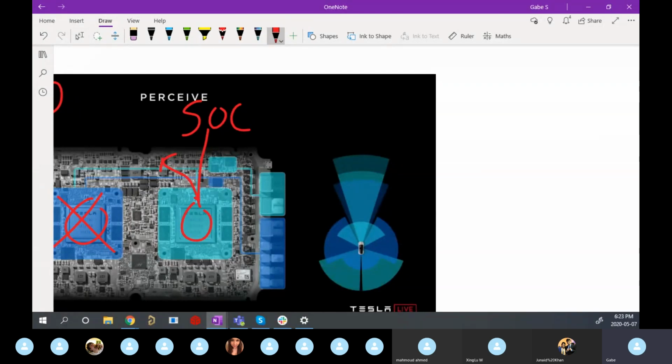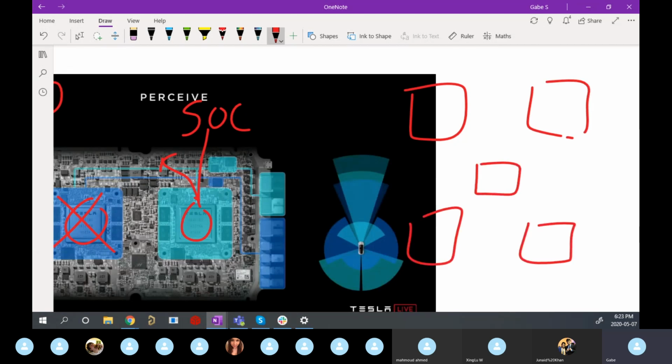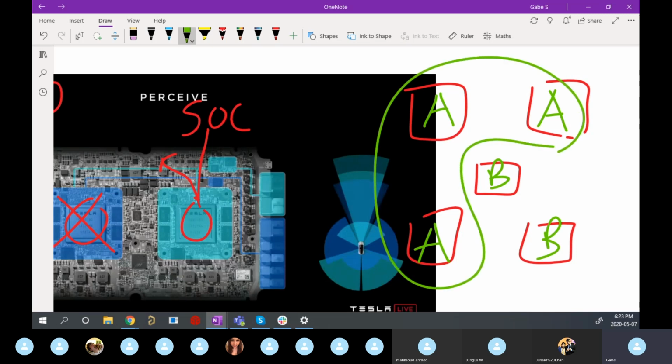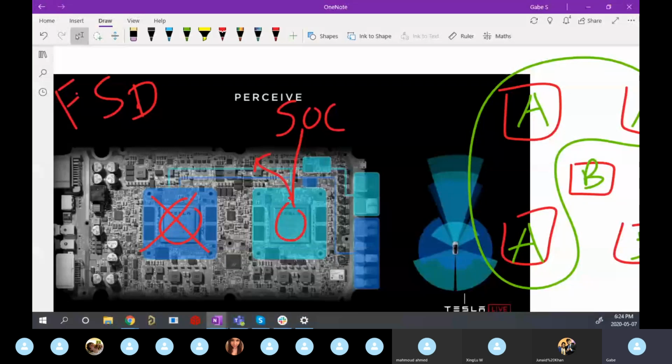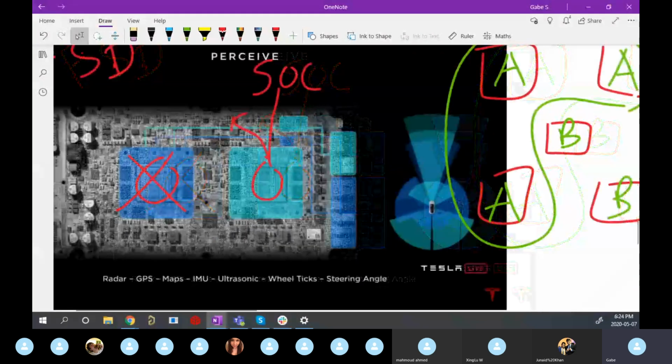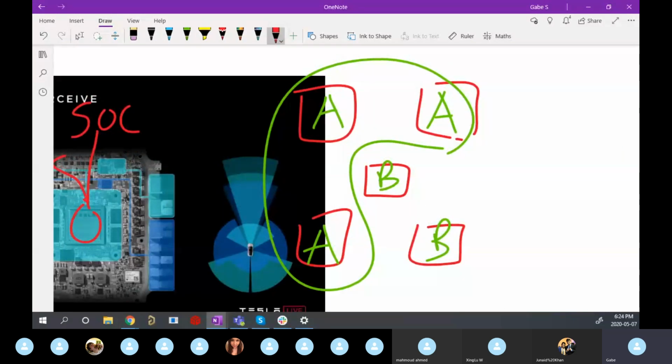And so what they do a lot of time is they have a redundant architecture, often with 3 or 5 different processors all running the exact same commands. And what this does is that if some of the processors disagree, then all of them vote on the best way to go, right? So if this guy says, I think we should do A, I think we should do A, I think we should do B, but these guys also say A, then you're going to go with action A, whatever that is. And so Tesla implemented the same thing in their self-driving car, just in case one of them breaks, right? So you have that redundancy. If one of them breaks, then the other can take over. Same thing here. You have up to 4 can break almost.